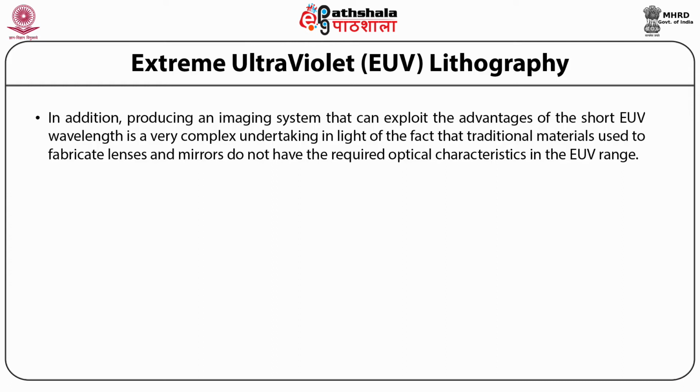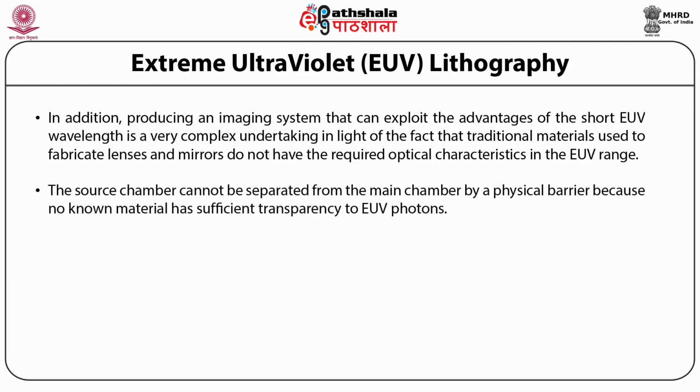So here the source chamber cannot be separated from the main chamber by a physical barrier because no known material has sufficient transparency to EUV photons.